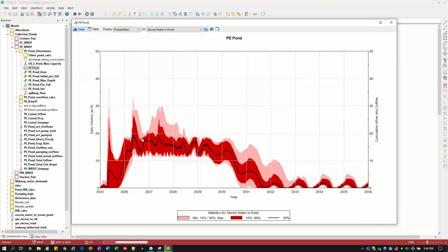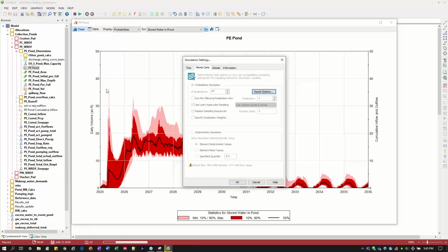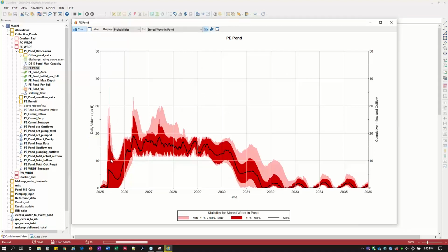And most of the time, in this example, we're maintaining kind of within this lower pumping level, but occasionally we get into the high level, and I cut it off early, but there's one scenario in particular, at least with the way this model's set up, where you'll notice there's a peak here, and this peak is controlling because there's actually a large amount of native runoff area, and that's a little more watertight material than the waste rock, which is obviously more of a chunky, potentially mixture of like gravels and sands and silty material versus the native area, which a lot of the Western United States and in a lot of mining areas in general, those native areas can be pretty exposed, shallow soils.